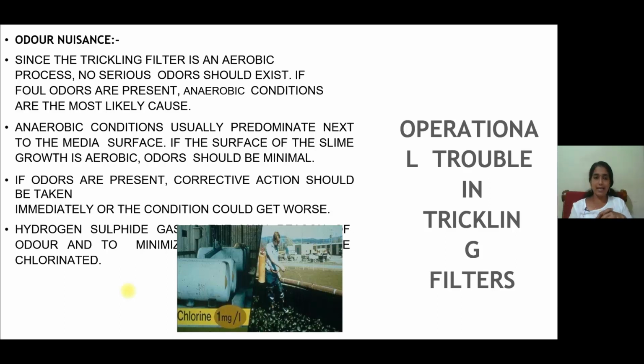Hydrogen sulfide gas will be produced due to this odor nuisance, that is due to the anaerobic conditions present in the filter media. And in order to minimize these conditions, the filter media is to be chlorinated.